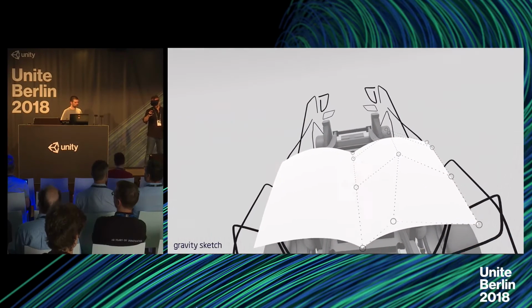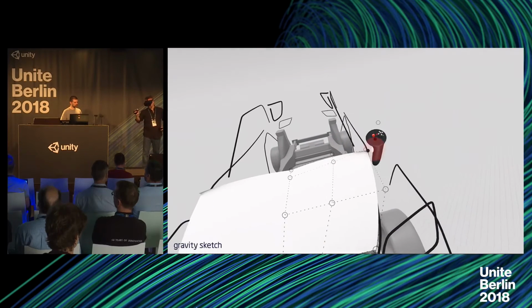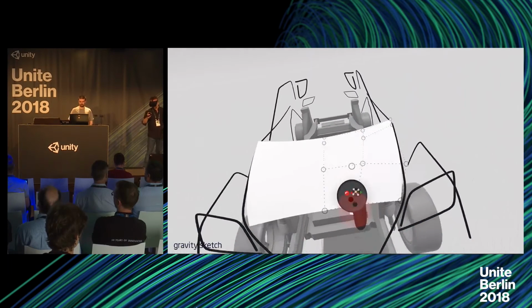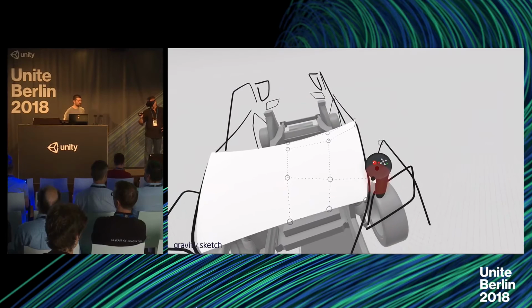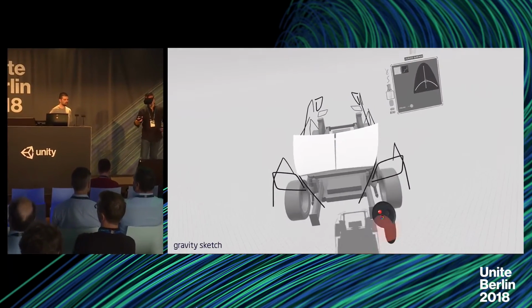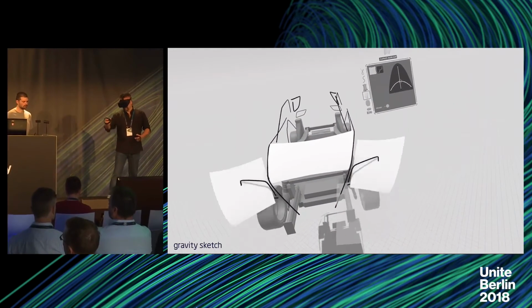As you can see, it snaps the points across the center line. So I do have the perfect mirror connection here and there. So if you ask what's behind that, there are no polygons. This is all NURBS geometry, which basically allows you to take these data directly to Alias if you want, and then do the refinements.